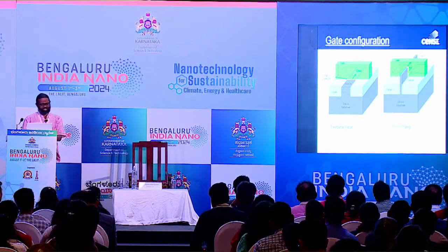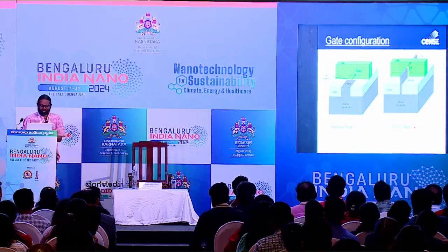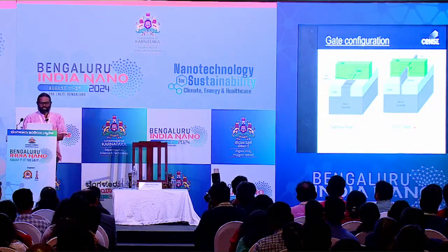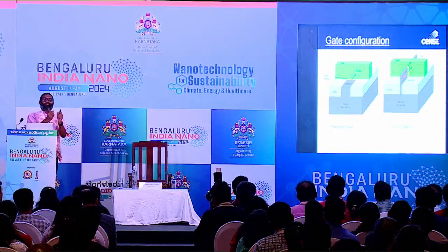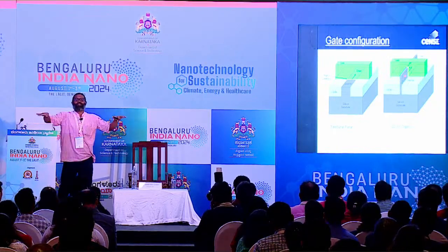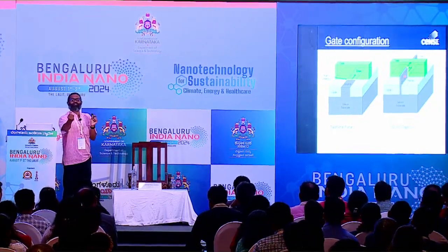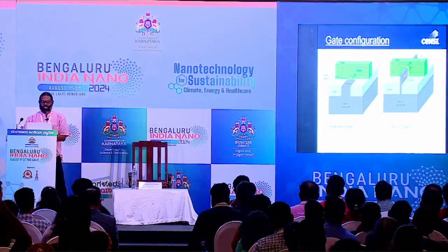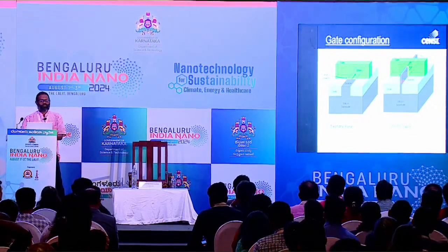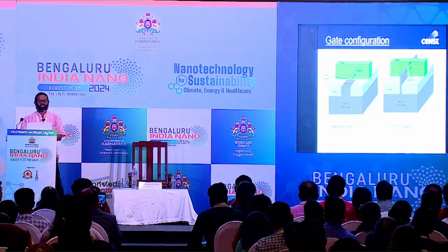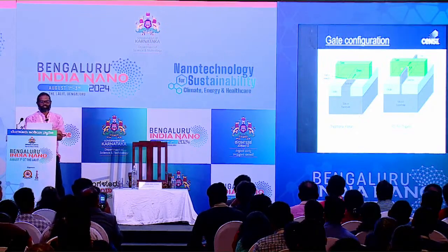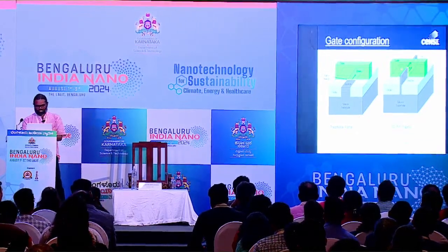and these days we have 3D transistors, FinFETs, Tri-Gates. There are many names, depends on the industry. So this is the fin. So instead of a planar, you have a very thin fin that's going to conduct, and you are going to control the flow of current by using this gate. All right. So pictorially, this is how it looks.